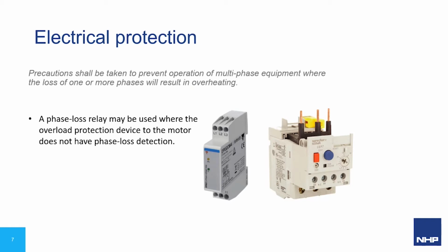Now, additional to the general requirements of Section 7, which cover wiring protection and phase loss protection, we also have further general requirements in 60079.14, focusing on rotating electrical machines, which we need to meet, as of course this is referring to motors.